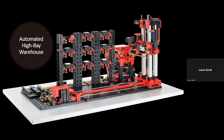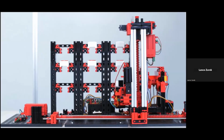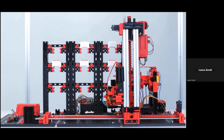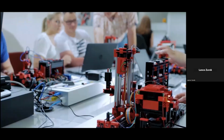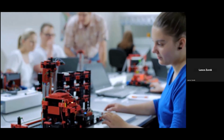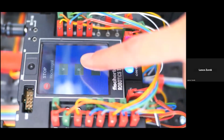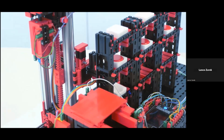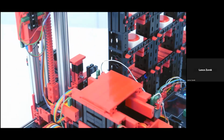Moving right along, the next model is going to be the automated high bay warehouse. The model you're going to see here features a transfer station with a conveyor belt, along with a shelf stacking mechanism for storing and retrieving workpiece carrier trays, along with 9 individual storage spots. Components on this model include 2 encoder motors, 2 mini motors, 4 push-button limit switches, 2 photo transistors, 2 LED light barriers, and a selection of different colored workpieces, along with carrier trays for each.